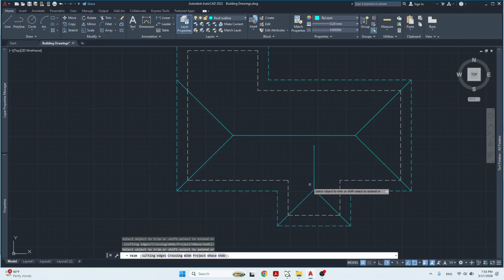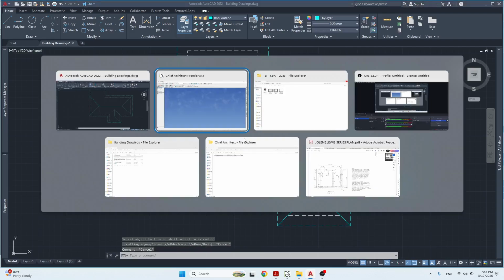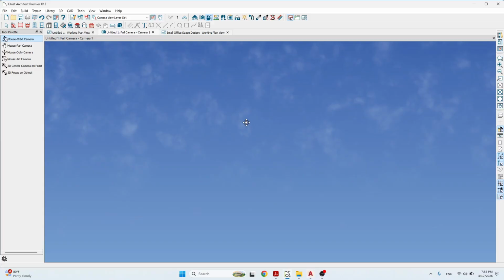We get that from the valley rafters or the hip rafters. Well, in this case, the valley rafters. So if I draw a line right here from this valley rafter, this corner, 45 degrees going up, and I do another one from here, 45 degrees, then right where they meet, that's where the ridge is going to stop.